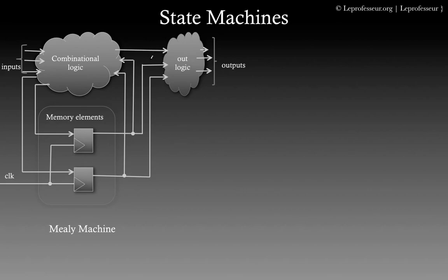So external inputs as well as the states become the input for the output logic. We can represent it another way: say X are your inputs and Q1, Q2 are the states of these two flops. Then the output would be a function of X, Q1 and Q2. So that's a Mealy machine. Notice that your output is not registered. It would be combinatorial logic based, because you are directly using the input along with the state outputs.